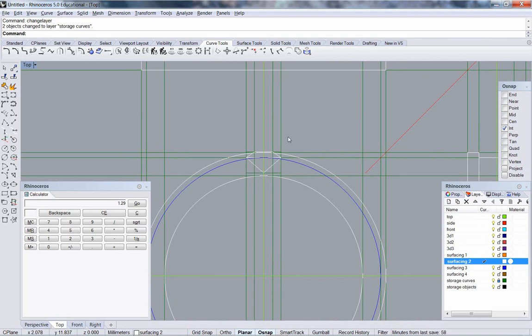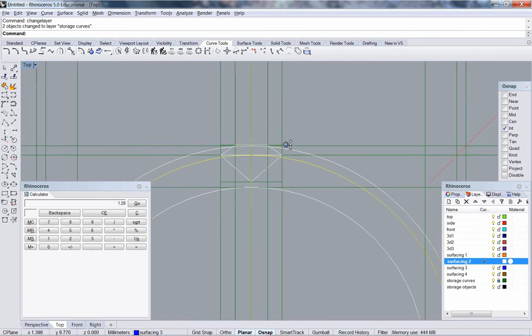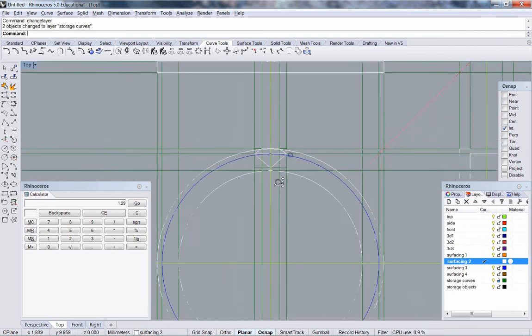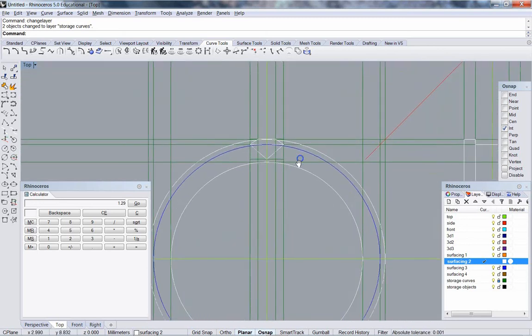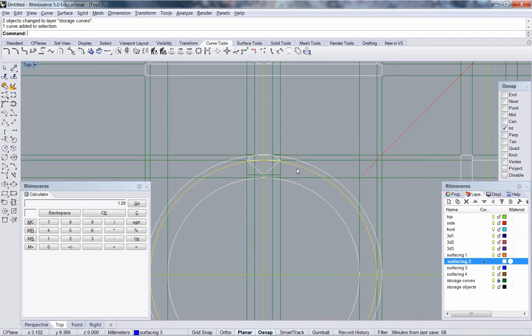Now, the challenge I have is I'm going to make these stones go around with a 0.2 millimeter spacing, between 0.15 and 0.2 millimeter spacing right here at the girdle line. The girdle line doesn't come in line with our tray, so we need to have a second hidden line. Actually, this is a hidden line because it actually exists in the drawing. It is actually this surface. Okay? So that's actually a hidden line. And if you were going to leave that in your drawing, it would be a dashed line. Okay?